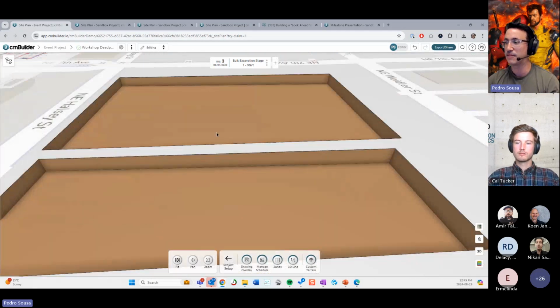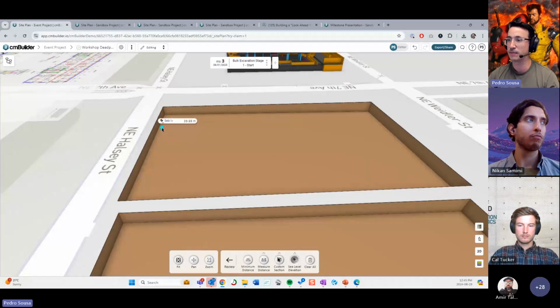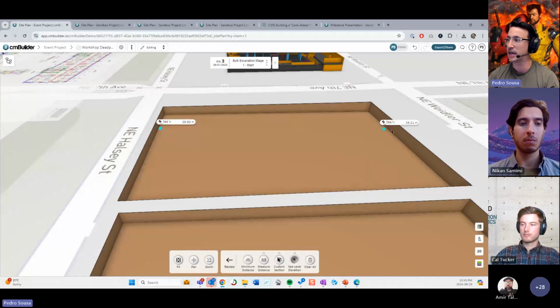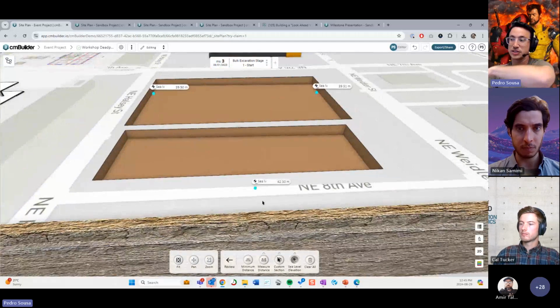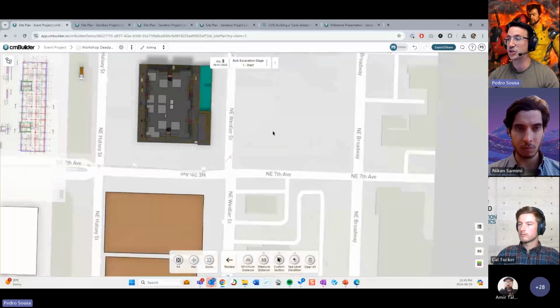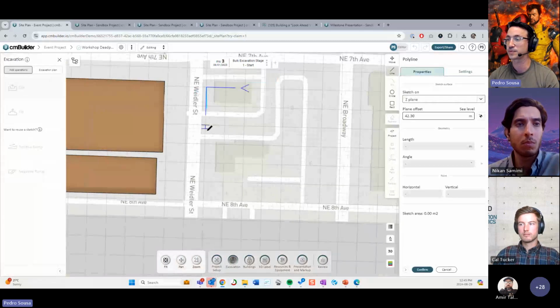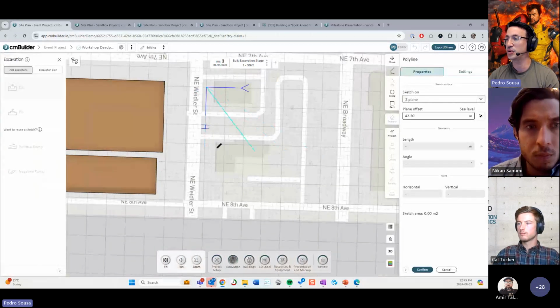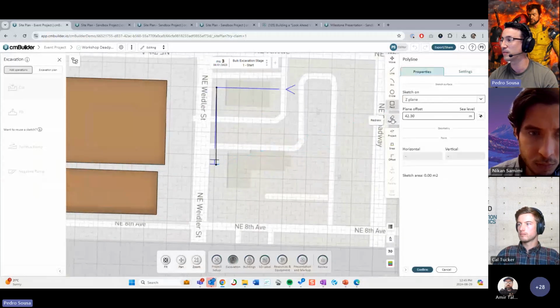But basically, if I measure in these two options the elevation on the bottom of your excavation at this side and at this side, you're going to see that the values are different, right? The bottom of the excavation is sloping uniformly towards one direction. To do that, you can go ahead and create your cut. There are two different ways to do that. I'm going to create a cut that is a little bit more uniform.